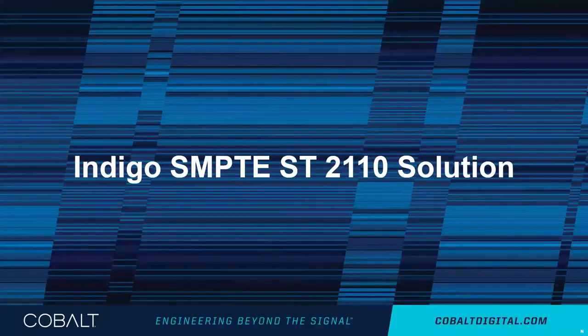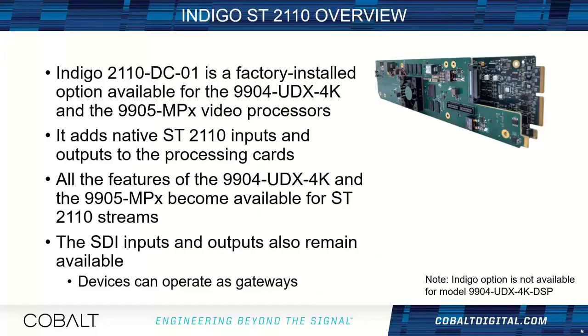Now let's dig into the Indigo ST 2110 solution. Indigo is a factory installed option available for the 9904 UDX and 9905 MPX video processors. It basically adds native ST 2110 inputs and outputs to these cards. So you now have a native 2110 solution that does everything the card does, but with input and output directly integrated into the card, which makes it a lot simpler.